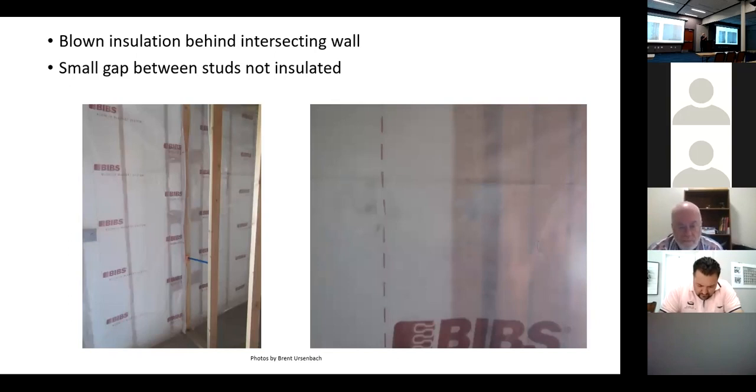And if we don't have a vapor barrier to stop the moisture from getting in there, then the moisture gets into the cavity and it's going to do what? It's going to condense on the back of the OSB. Now, does OSB love water? It sucks it up and it goes to hell, right? So we get condensation in walls. Now, the intent is we put a vapor barrier on it and we stop it from getting in there.